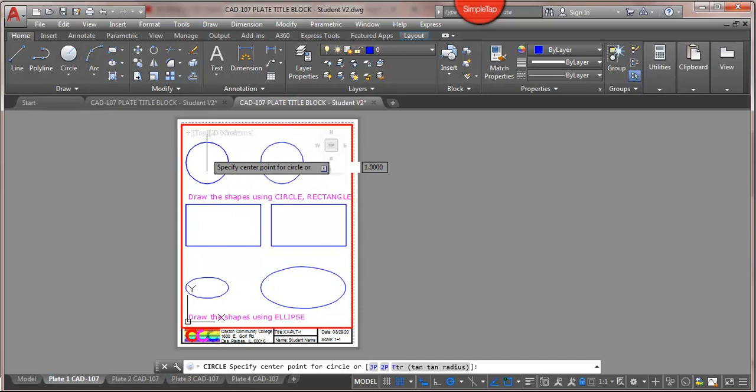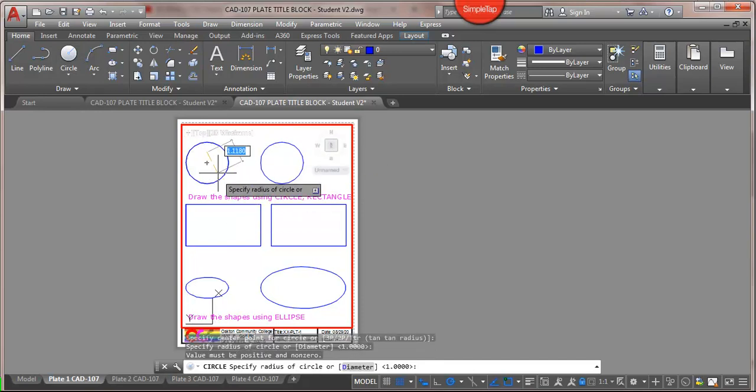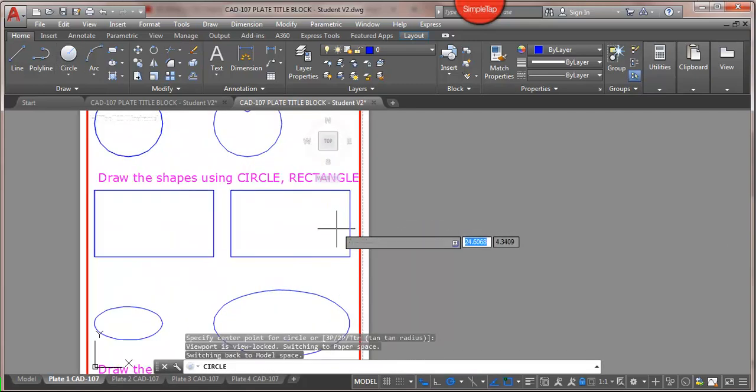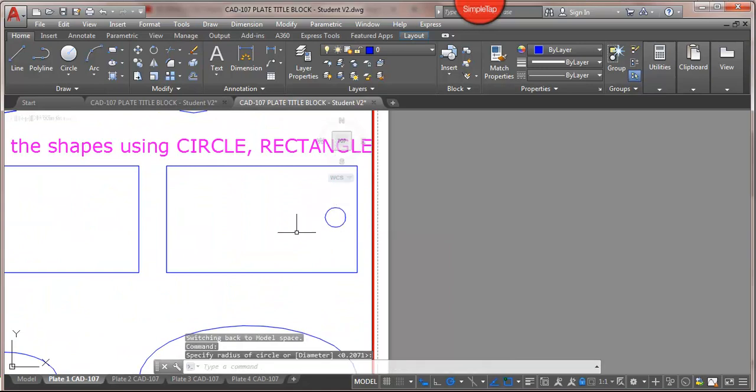make them able to put a hole through it. Now, one of the things that you'll notice is that it snaps. And so you're like, hey, every time I try to draw something, it's on this grid. To turn off the snap, we can just type in the word snap, S-N-A-P, hit enter, and then hit the down arrow and turn it to off. When the snap is off, you're not constrained by a grid or numbers. It'll draw whatever you want. So turning on and off snap can be a useful thing.